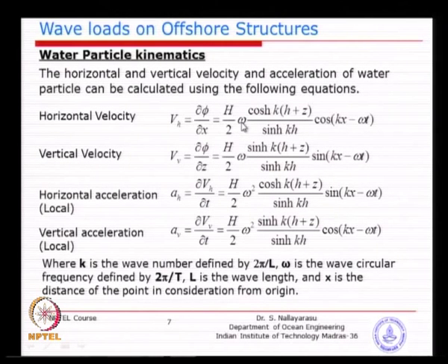If you know the wave period, you can calculate the wave frequency, and then the wave number can be calculated as long as you know the frequency, the wave period and the wavelength. The water depth is also known to you, along with the elevation at which the wave load or velocity is required, and the time of wave propagation. So all the parameters are known to you.